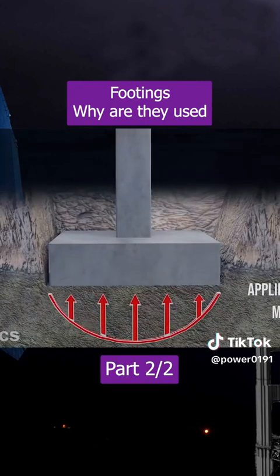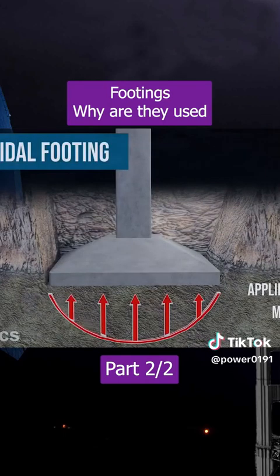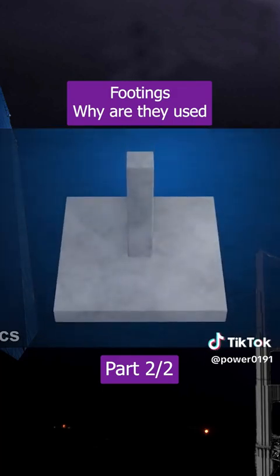Thus, the need for footing thickness in the center is greater than at the edges. Therefore, a trapezoidal footing shape has been adopted in modern structures for isolated footings. However, a pad-type footing is used in other more complex types of footings.